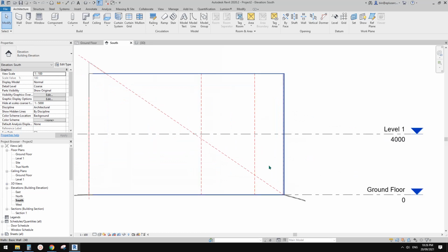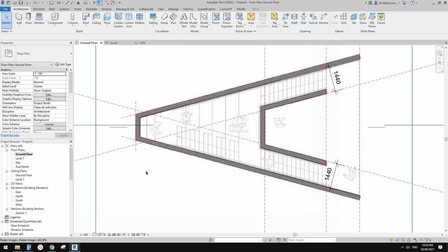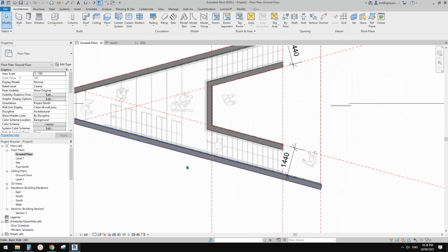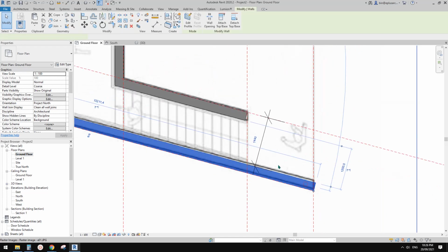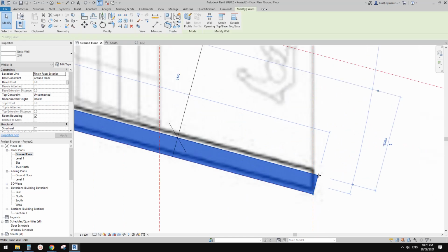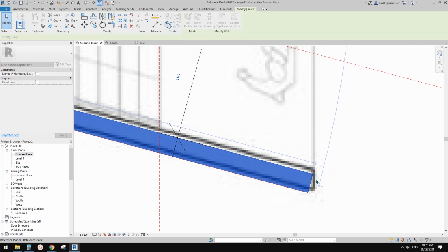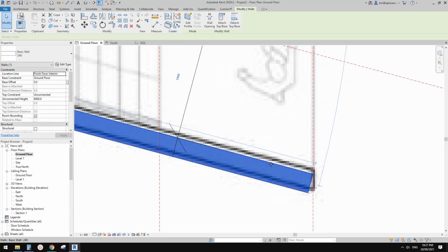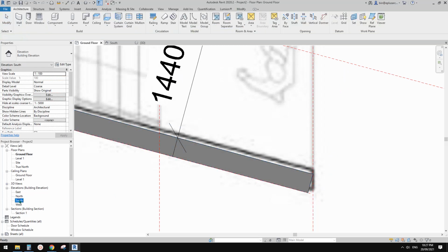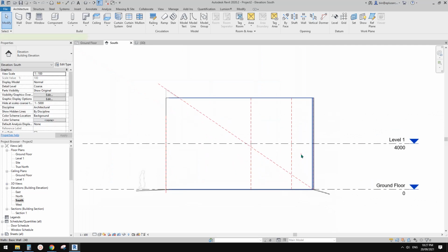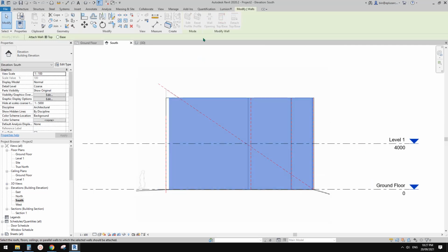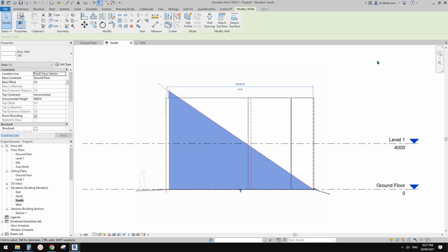So your option is you can just drag this wall back to make sure you see this part. If I change this to interior, we can drag this back to match this reference plane. This way you can align, attach top to the reference plane. Okay.